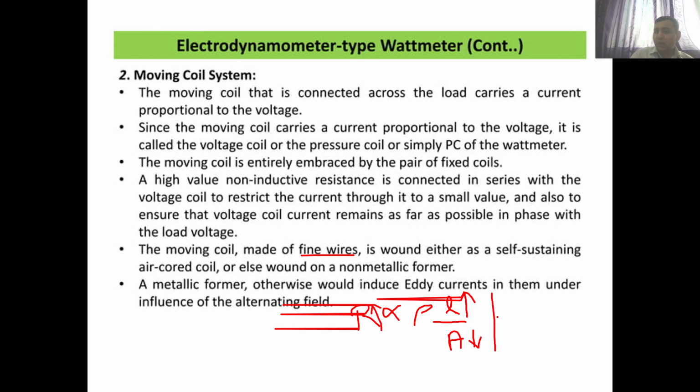In the case of the fixed coil, where we want the ammeter to have a very low resistance path, we want the resistance to be low, so its area of cross section should be large, or the wire should have a thicker diameter, and the length should be small.